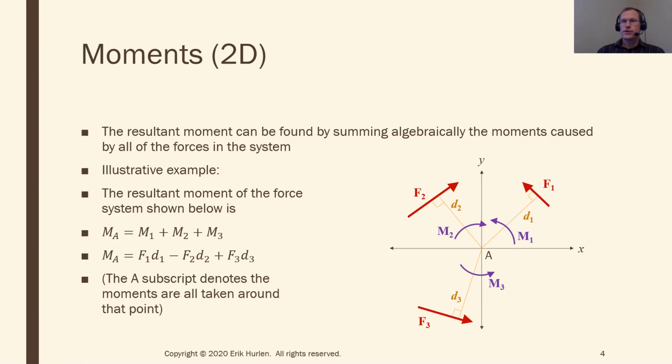And just like forces, usually for equilibrium, for example, I want to take the net force, the sum of all forces. I'm also going to want to have a net moment. So I want to find the sum of all the moments acting on an object. And to do that, it's very similar. For net forces, I just take all the forces and add them all together as vectors. Technically, for moments, you do the same thing. Take all the moments and add them all together, again, technically as vectors.